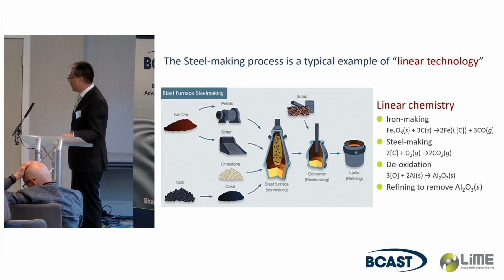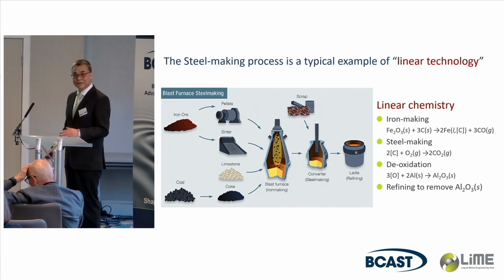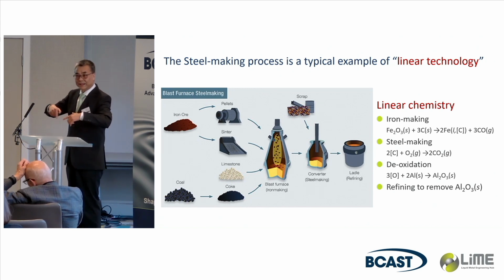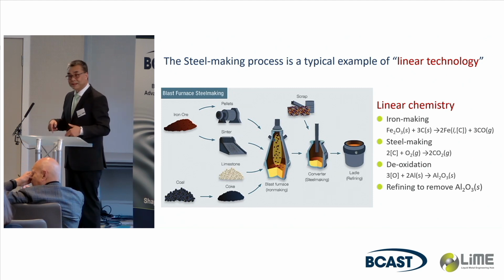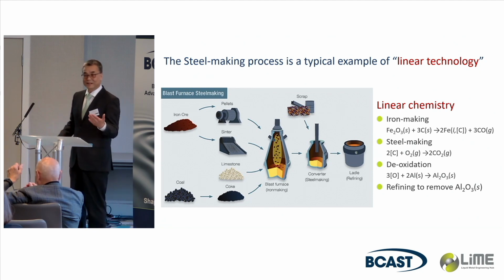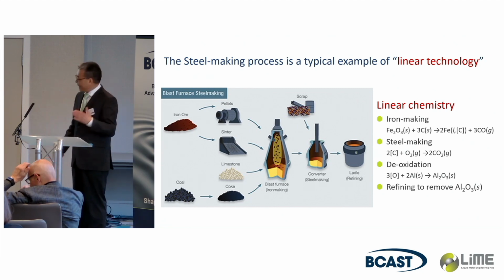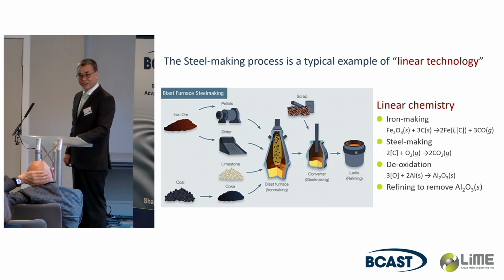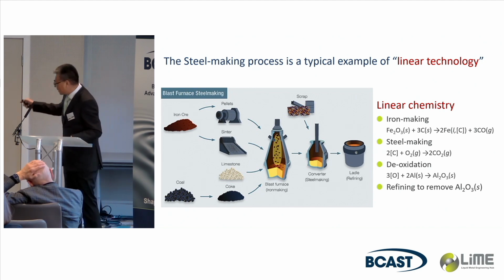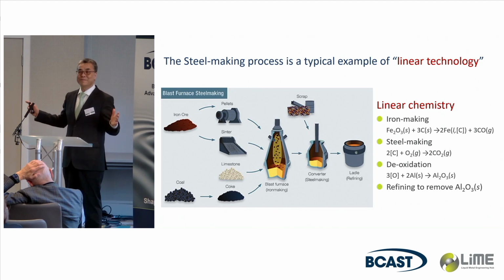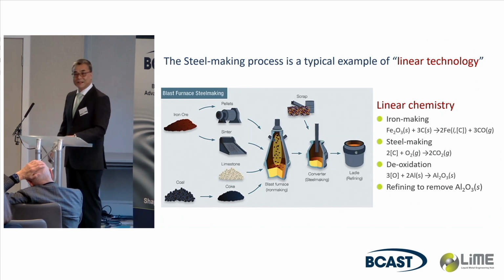It's very brittle. And then what do we do? We don't like this carbon, so we blow oxygen into it. And of course, the carbon is burned out, and oxygen is up. So what do we do? We put in aluminum, magnesium to deoxidize. And dissolved oxygen is down. But the problem now is we end up with bigger trouble, which is oxide. And the purification process after that becomes the major problem for the steel making industry, okay?